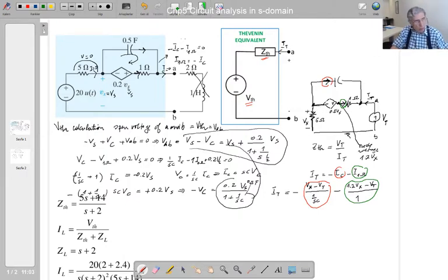So I am saying it by using the Kirchhoff current law equations, not that the current is divided into two groups, two branches, but by using the Kirchhoff current law equations, I am saying this current is equal to this one. So that means now this is equal to IT. Well, that's a good conclusion, saying that Vx then is equal to 5 times IT. So if you replace that Vx with 5 IT, that means you found your equation.